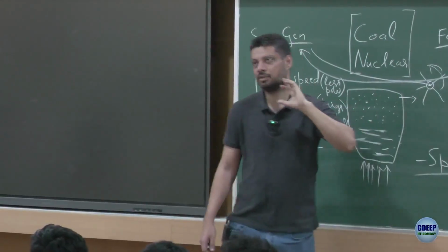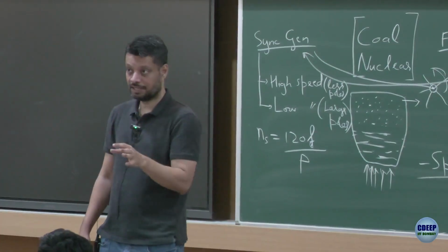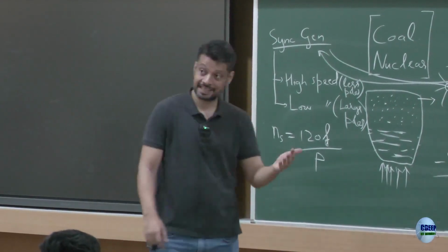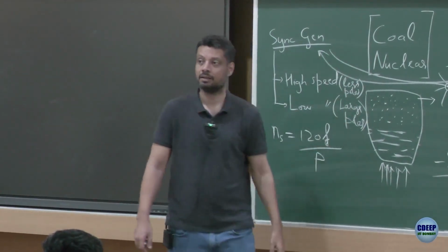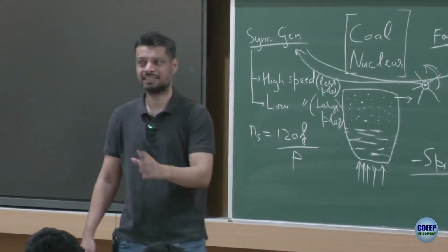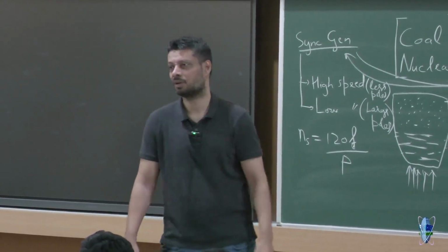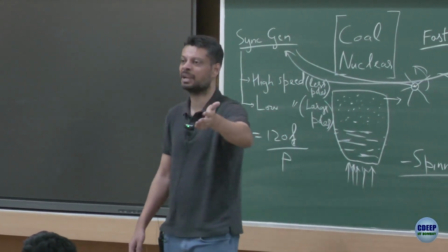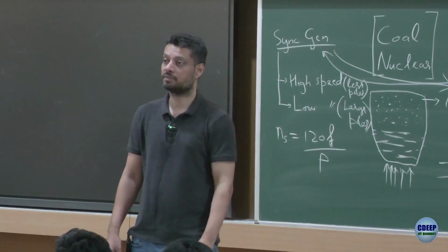You would directly burn gas and use it to run a turbine. Once the turbine is rotating, whatever comes out of the turbine is still relatively very hot. You can use that as a secondary cycle to build steam and then run a secondary turbine. You can do that, right? So you can have a direct burning plus a steam cycle for gas. It has a specific name, some combined something which I'm not able to recollect, but you can search for it. But yeah, you do that with gas to improve the efficiency, because the gas coming out is still hot, you can still use it and produce steam.